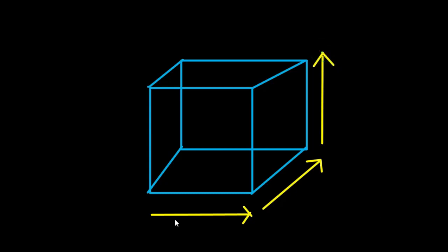So all the dimensions, let's assume that this side is 10, this is 15, and this is 10. So all of them are comparable with each other. Either one is not very small or very large. So that's why we can say this problem is a 3D problem. So we can directly go and solve this problem in 3D itself. So this is the methodology to choose whether I should solve this problem in 1D, 2D, or 3D.